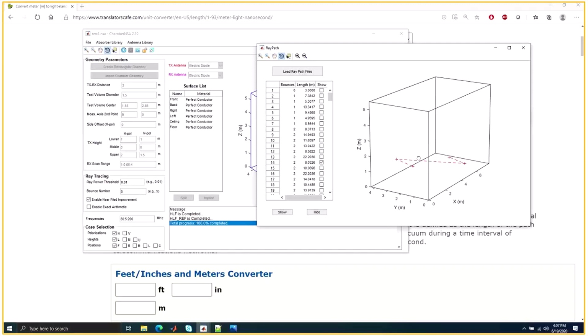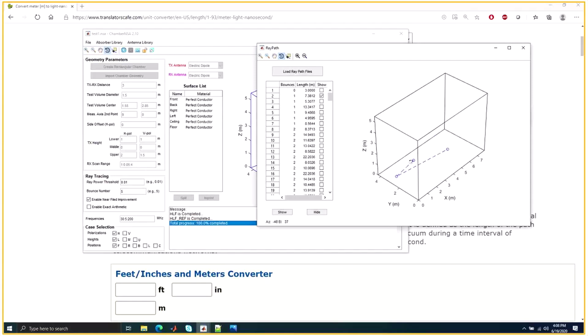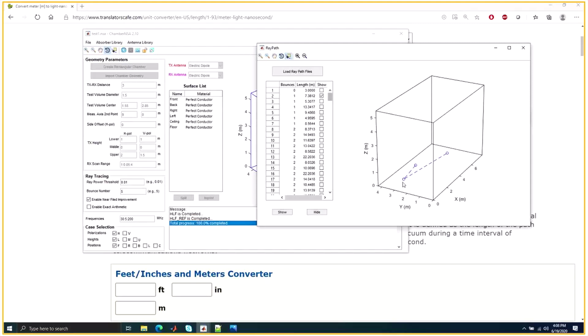to look for or work on if your reflection spike path length came out between 8 and 8.5 meters. But in our example, we already calculated that the path length was 7.38 meters. We definitely know that it was this. We can narrow it down to this particular reflection spike and say, okay, this is the spot where the exact reflection is occurring, and then we can go inside the chamber and put some absorber on that spot and around it to see if that makes a difference in the chamber performance.